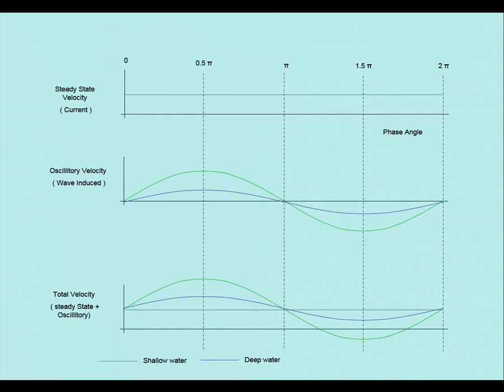And in shallow water, how shallow are you coming up near the beach? Because when you get near the beach, when the wave height is 7/8 of the water depth, the wave breaks, and the mass of water then will run to the shore. So, but yes, it could well be more dangerous than in deeper water. Stability is not so much a problem.